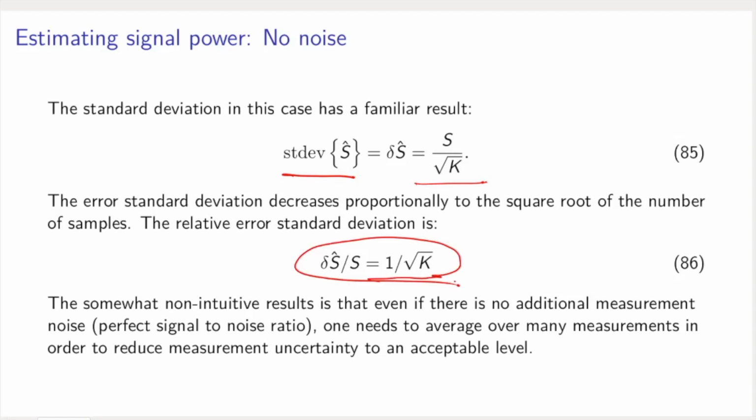One important note to make here is that we assume no receiver noise. Even when there is no additive noise, our estimator has errors. This is because we're estimating the variance of the radar echo, which in itself is a random process.